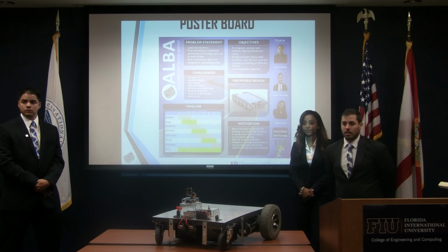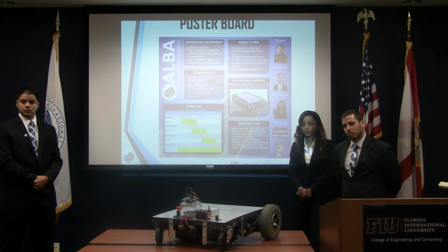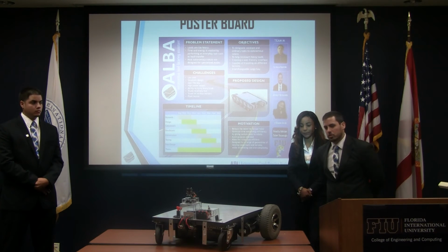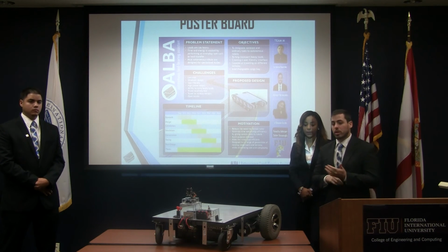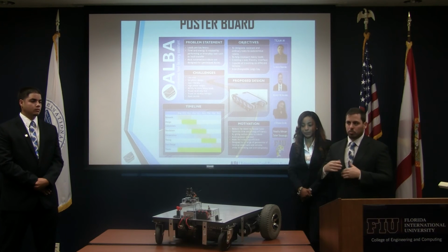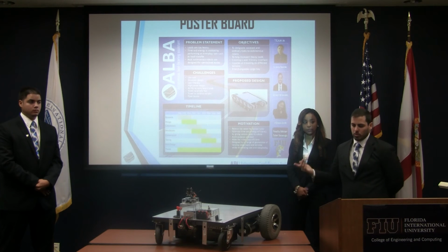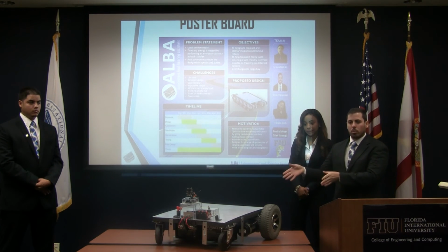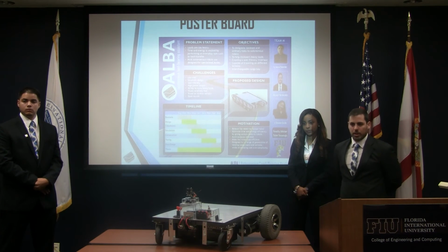For your specific load, what's the power requirement to actually move this? We took the specs off of the wheelchair motors, where basically it provided a maximum, I think, 397.5 pounds to go 5 miles an hour. We compared the specs on the wheelchair motors to the weight of the actual robot and used that information to predict how fast it was going to go.